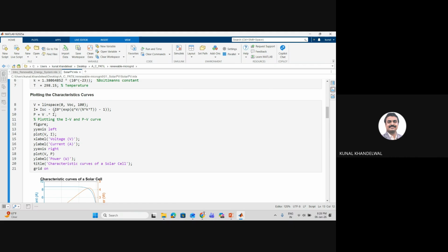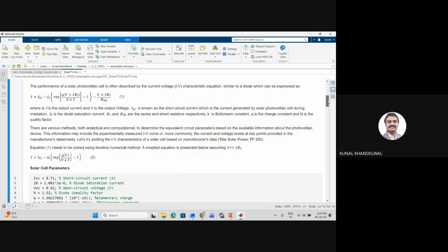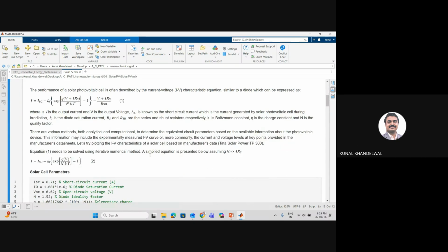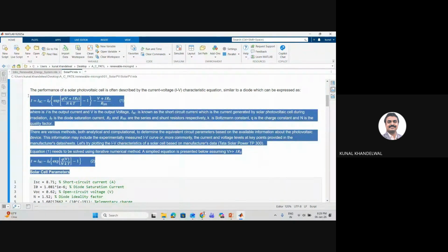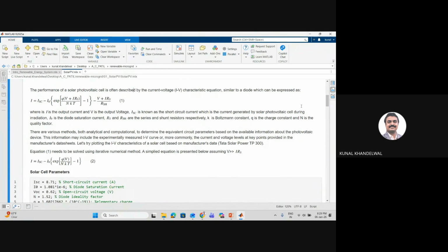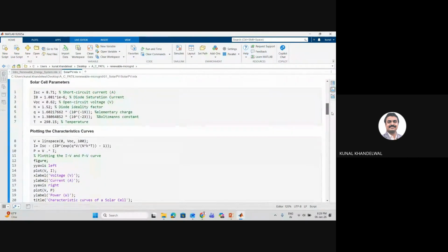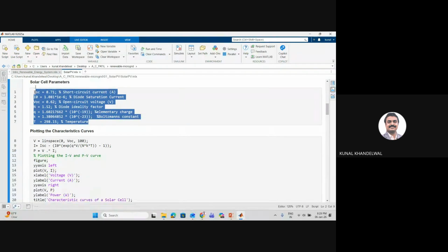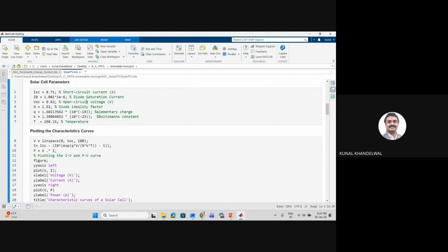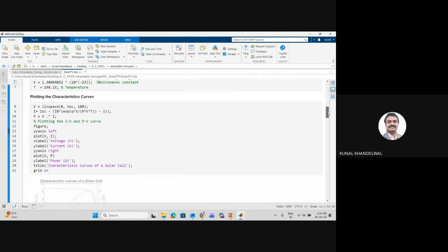So how to run this particular section? You can press Control Enter and you can click on this blue bar over here to execute this section. And one more thing that I want you to focus upon is, see the entire text where there are no numbers on the left hand side. This is text, these are comments, right? And whenever you have numbers 1, 2, 3, 4, 5, 6, 7 under this gray color part, this represents code. So let's click on this. What I'm expecting at the output is that I should get IV curve and PV curve.